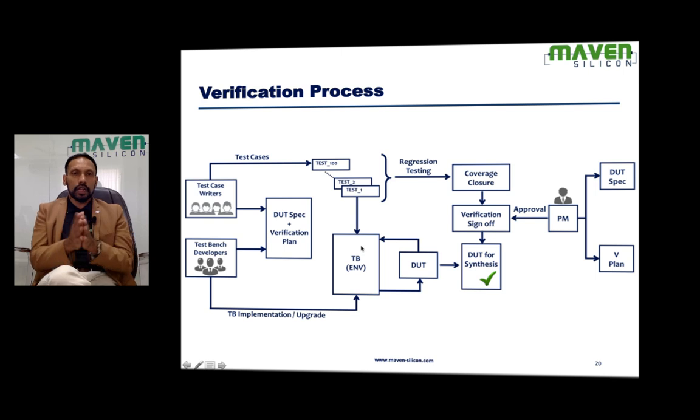And once the verification environment becomes stable, what they are going to do is write some basic test cases, and then verify whether the Testbench works properly, whether the data flow happens properly. Once the verification environment becomes stable, then they will inform the test case writers to write test cases and run simulation. So these test case writers, usually they are junior verification engineers, so they refer DUT specification.